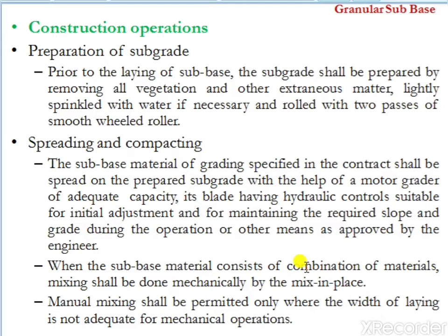If there are any pores or voids in the layer or course, they will be filled with soil particles. Hence, the subgrade will become stiff and strong enough to take up the loads coming from the traffic. What's the second step?